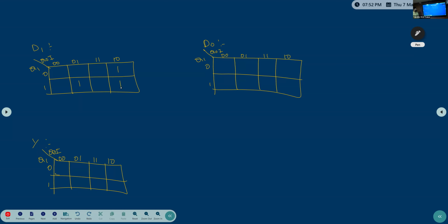Okay. So now mapping will happen. So how will it happen? Maximum I can map these two, right? So what is common in these two? Q1 is common. Q0 to 1 it is changing. I is 0, so I bar. 0 means bar. If 1, then no bar. So Q1 is 1, Q0 is 1, that's why Q0. I is 0, that's why I bar. Clear? But one more 1 is missing here.